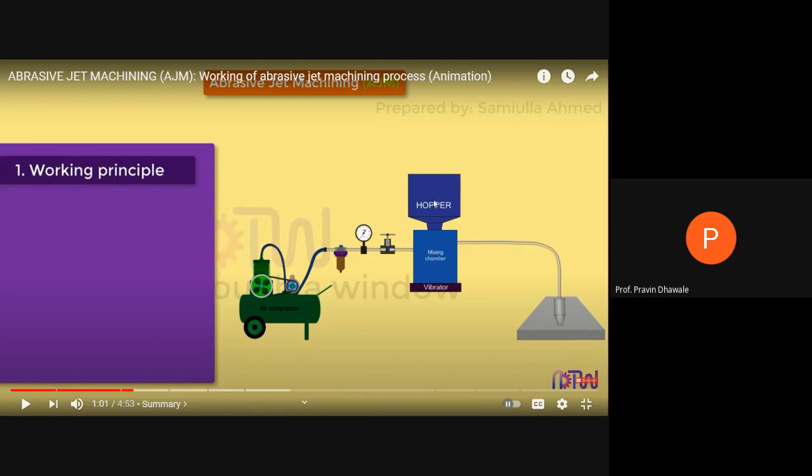When this high pressure air along with the abrasive particles are mixing over here, the high pressure abrasive particles along with air come through this nozzle, where pressure energy is converted into kinetic energy. At the nose of the nozzle, you get a high velocity abrasive jet. When this abrasive jet strikes the work surface, the material of the workpiece is removed by the action of mechanical erosion. So material is removed from that specific area.